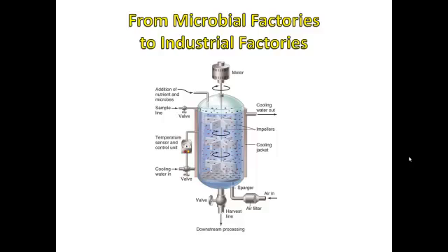This figure shows an industrial fermentator. Nutrients and microbes are added here. A water jacket is used to keep the fermenter at the correct temperature. Air is bubbled in at the bottom of the fermenter so the microbes that must use oxygen to make their product have enough. The harvest line routinely removes the product and microbes, of course. The microbes are removed from the product most of the time. You want to be injected with pure, sterile penicillin, not the penicillium mold.